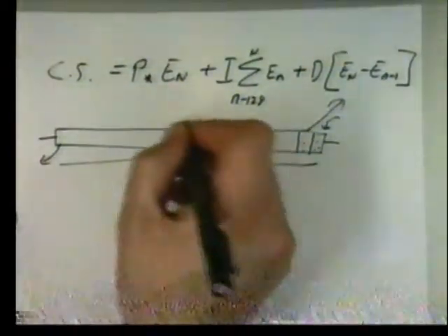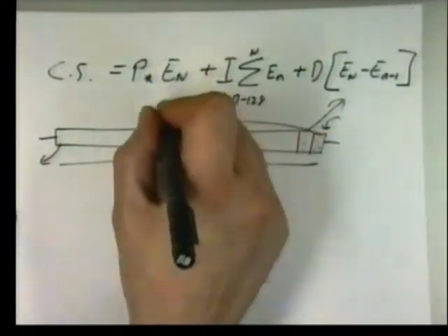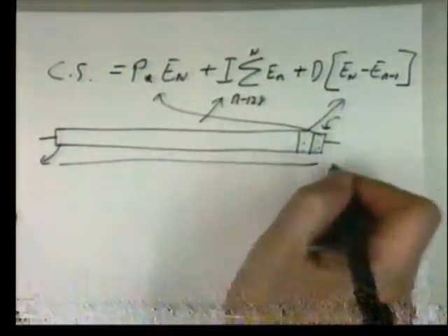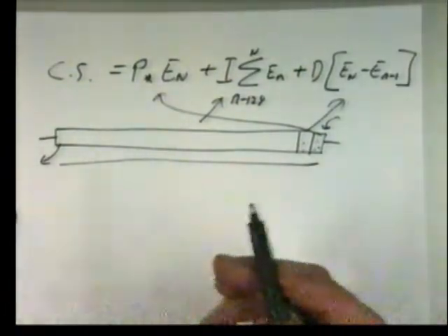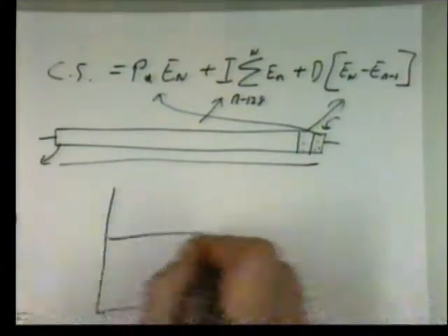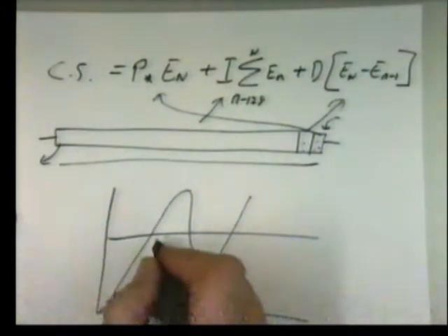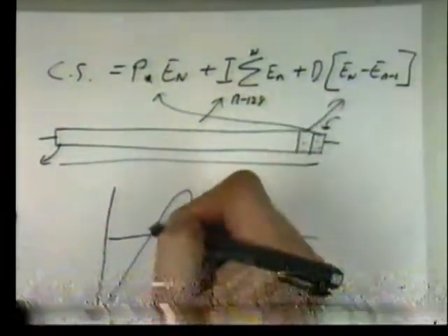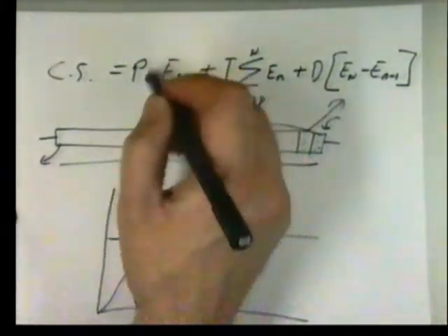The sum of the whole of the array gives us our integrator term, and the most recent sample is our proportional term. So you can do the whole thing very easily within an array and a couple of pointers running around the array. Very, very easy coding to do. And what happens with our response? Well, if we were going to be accelerating away, the derivative term again only starts dominating near the set point, with small errors. If the errors are large, the P term will always be the most dominant factor.